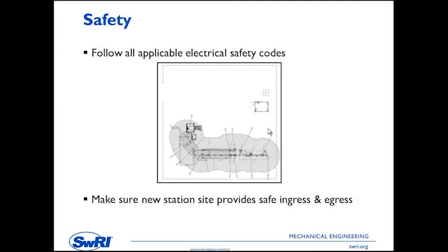One of the things I don't like about this particular layout is that I would have located this control building somewhere over here. This would accommodate running straight runs of conduit in a single ditch instead of having to perhaps run your conduit trenches in a 90-degree turn where you may have to install more conduit. So from a cost perspective, you have some cost savings if you can simplify your layout of your facility.